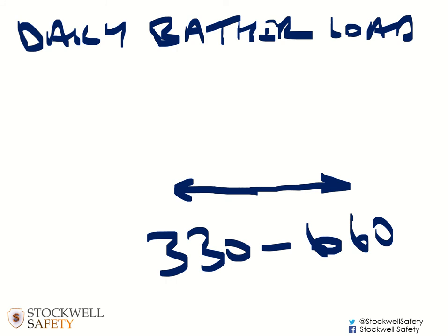But if you're fully aware that bathers don't tend to take a shower before they go into the pool, then they might be contributing twice the amount of pollution than another bather that is taking a shower before they go into the pool. And in those sort of circumstances, perhaps it would be a better idea to keep it towards the lower end of that range. But experience will tell you what is appropriate.